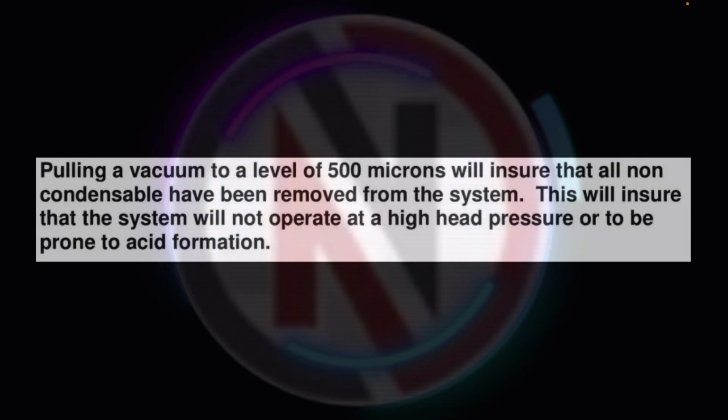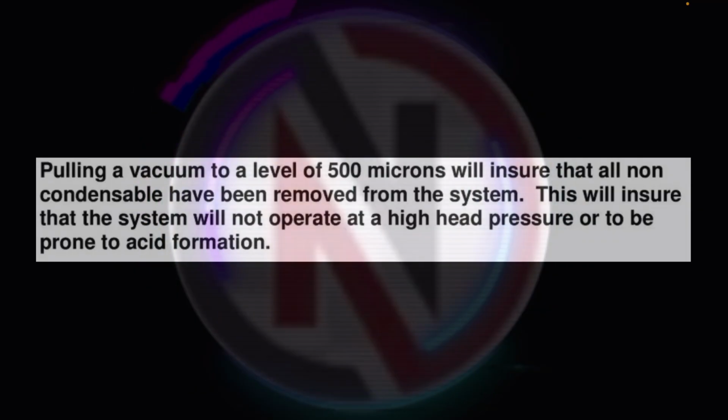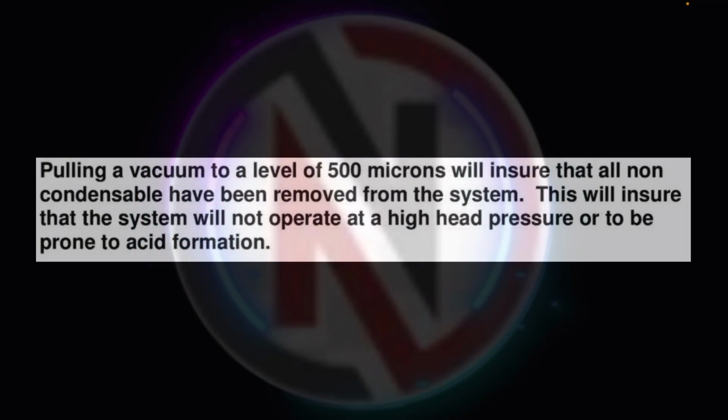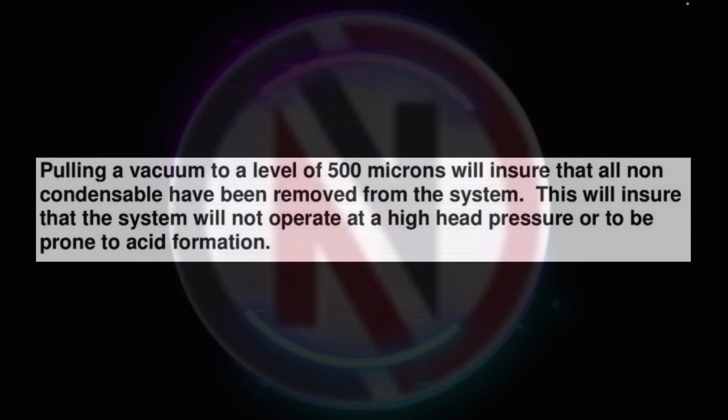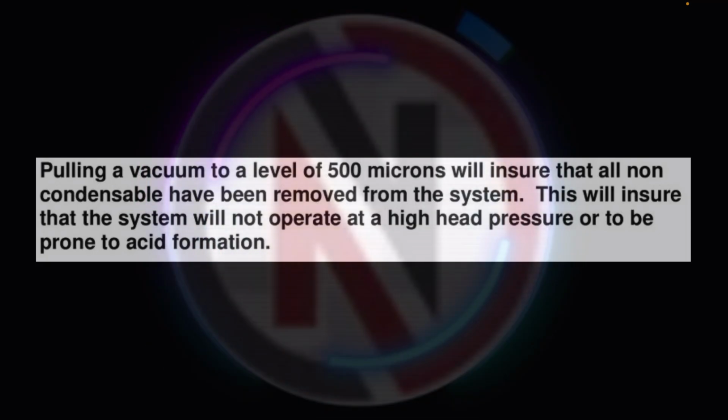Pulling a vacuum to a level of 500 microns will ensure that all non-condensables have been removed from the system. This will ensure that the system will not operate at a high head pressure or be prone to acid formation.